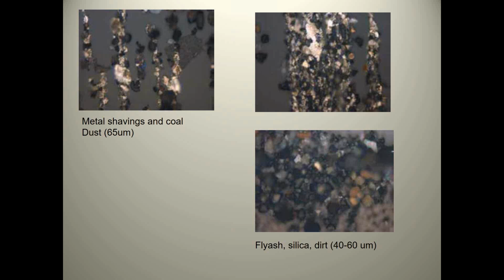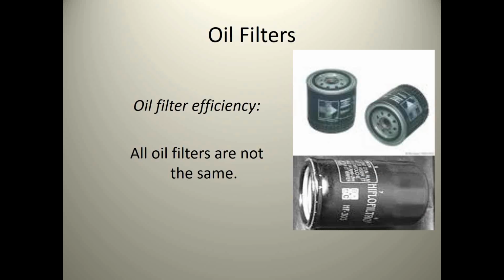Now, if you want to know some other things about your oils and this sample, that may be all right, but these particles, like this one in the lower left-hand part of the picture, are going to cause a gearbox to fail in probably a month if you have that level of fly ash, silica, and dirt in gearbox oil. And like I say, if you can see it in there, you've got some big wear particles.